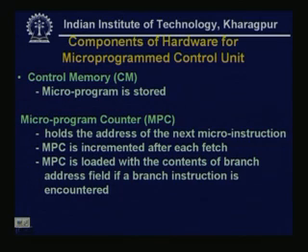The MPC is similar to a program counter. So, MPC is incremented after each fetch. If a branch instruction is encountered, the MPC is loaded with the contents of the branch address field of the micro instruction. So, this is the function of a microprogram counter. In short, we can think that MPC is just like the PC, the program counter of the CPU.